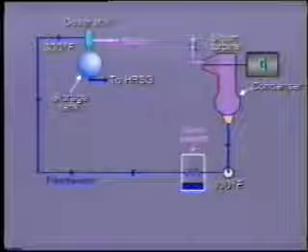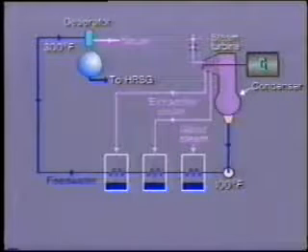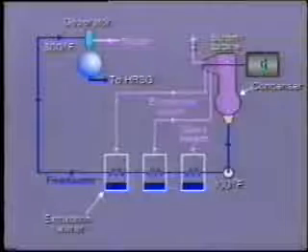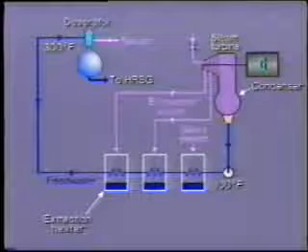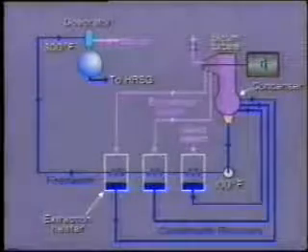In some installations, feed water heating is employed using steam, which is extracted from the turbine. You will no doubt be familiar with extraction heaters as employed in conventional steam power plants. 2 or 3 closed tubular heaters are installed with condensate passing through the tubes and steam flowing over the outside of the tubes. The condensed steam from each heater is returned to the condenser hot well to become part of the condensate stream.